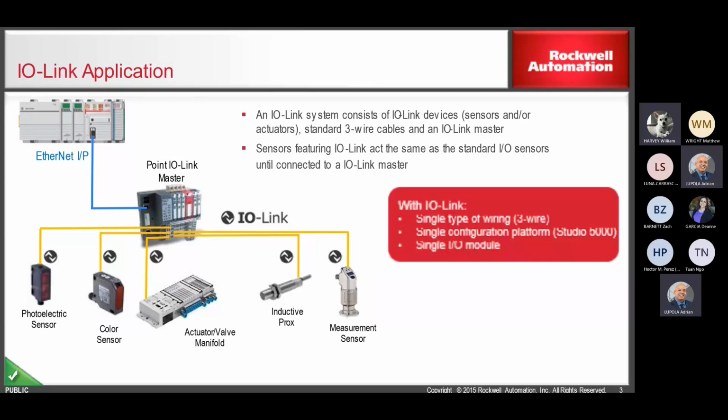But over the standard 4-conductor cable that you hook to all these sensors, and a lot of our standard inductive and photo eye sensors, it's the same sensor. If you hook it up as a dumb sensor, you just get the on and off status or maybe an analog value out. But if I go over IO-Link, I get sensor health. You can turn things into counters and timers built into this. Again, you can get margin indication and a lot of diagnostics of what's going on with the sensor.